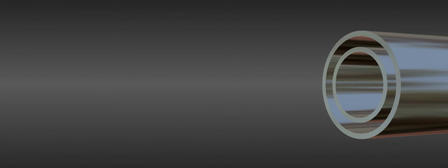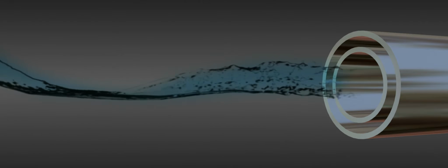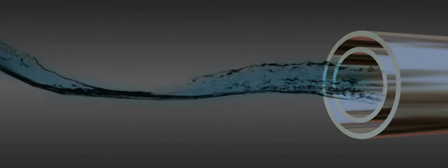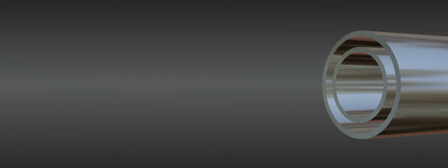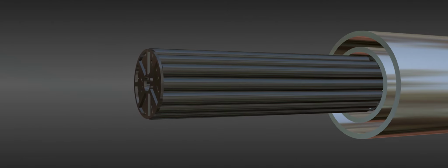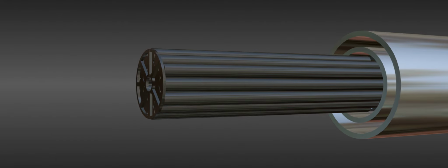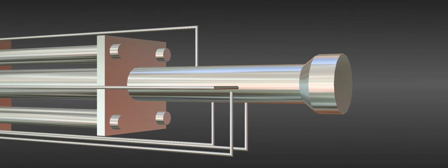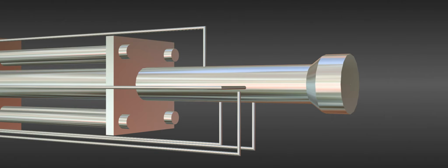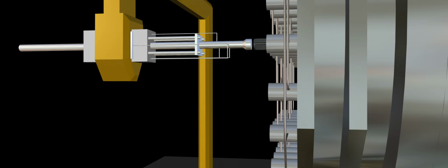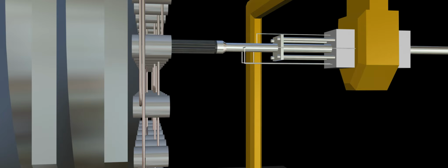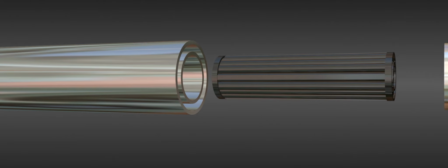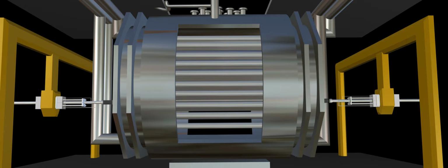The coolant tube has mainly two things inside. One, the heavy water flow that helps to transfer heat to the steam generator. Two, the fuel bundles that generate heat by fission process. Loading new fuel into or removing spent fuel from the reactor is carried out by two fueling machines at both ends of the calandria, which are computer controlled. The loading is done through remote operation as a radiation safety requirement.